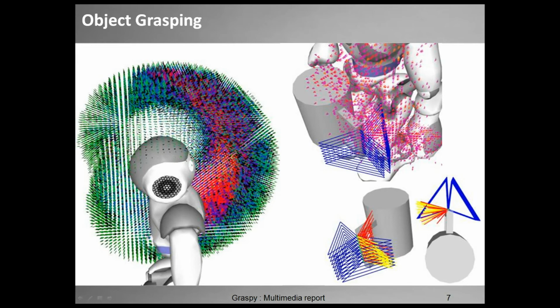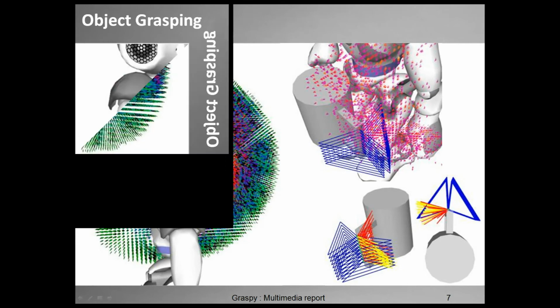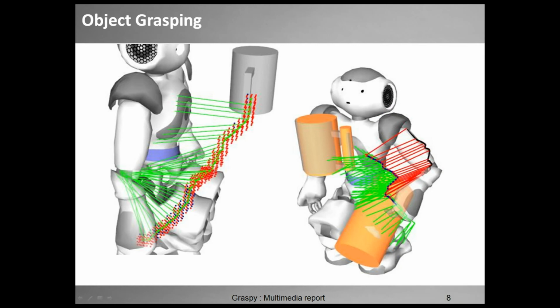Each subcube serves as a region in the workspace and stores possible hand rotations per hand position area. In order to select a grasp, possible grasp points are matched with the reachability map, and checked whether the corresponding possible lower arm directions are qualified for the grasp. The reachability map provides the grasp motion planner with 6D information on the possible hand positions and lower arm directions.